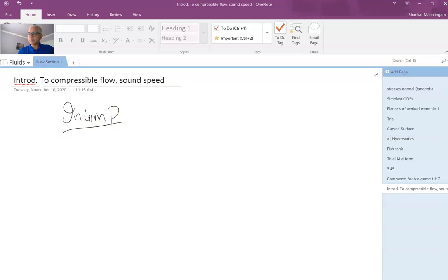In the case of incompressible flow, let's look at the equation count we have. In this case, rho is a constant. So what we would need is conservation of mass. That gives me one equation. We would have Newton's second law in each of the three coordinate directions, so that gives me three equations. And let's look at all the unknowns in our problem. The unknowns will be the three velocity components, u, v, and w along the three coordinate directions, and also pressure. So we have a total of 4 unknowns.